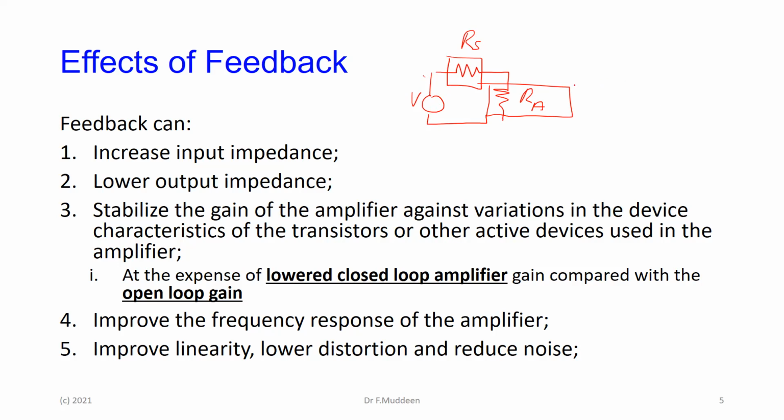When you put that to a circuit, and in our case we're dealing specifically with amplifiers, what you want anytime a source is connected to the input of some other circuit is that the input impedance of the circuit must be much higher than the source resistance or source impedance, because simple voltage divider theory will tell you that if RA is much bigger than RS, the majority of the signal is going to appear here.